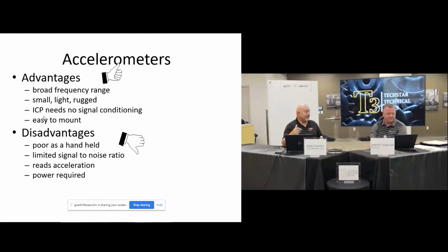So you have to convert to velocity or displacement depending on what you're doing, because you have integration one time to velocity, double integration to displacement. And you do lose a little value to your data that you're collecting by doing that. But if you're consistent, you base it off your consistency of your data, and your information should be good.